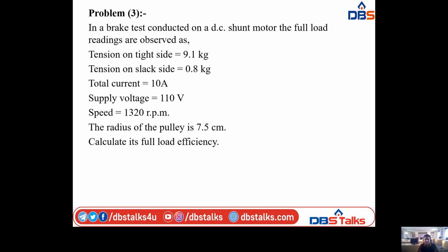So take the same here, that is RSC is equal to V by I1. Here the voltage is 15 volts, I1 is 40. So finally we have 0.375 ohms. And total copper loss for the motor and generator is (RA plus RSC) into I1 square plus I2 square RA.